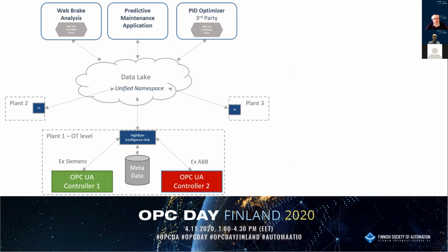What I mean by combining is that sometimes you have, for example, a CNC that has an OPC UA server on it, but it also might have an OPC DA server that handles the load/unload robot, and that might not be fully integrated in the CNC. So already on the same machine you have two different data sources that you need to combine to provide good quality data to the cloud applications.